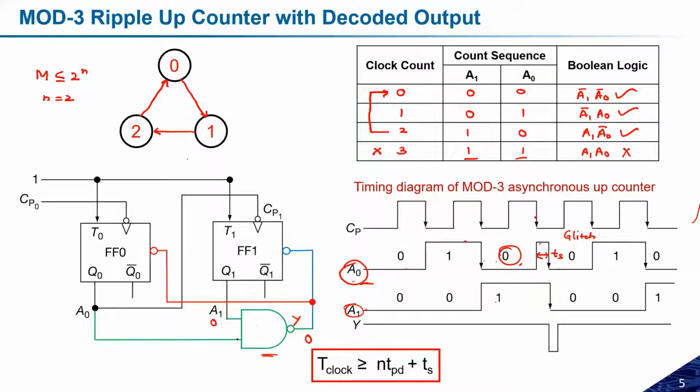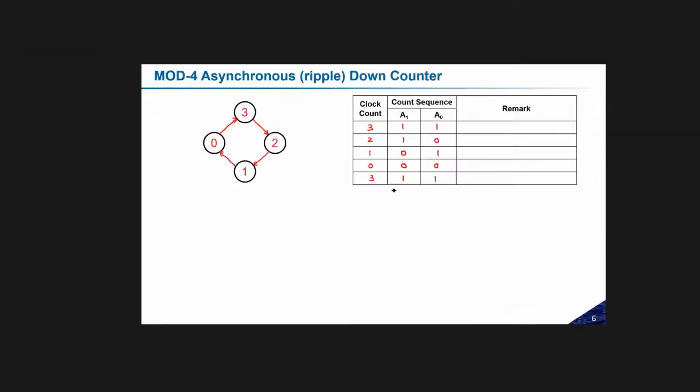Like if there are 2 flip-flops, the total number of sequences will be 4. So 0, 1, 2, 3, then it will come to 0 and so on. But if you are using some additional circuitry, then this may change the number of sequences that the counter will follow. So the number of sequences depends on these things. Let us try to consider those things.